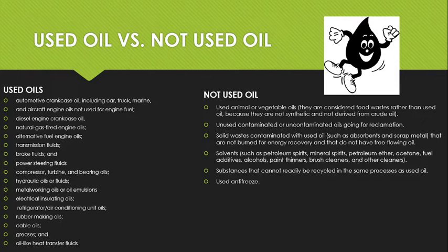So you just really have to pay attention to what you're putting into your oily water, what you're classifying as used oil, because you don't want to screw up a whole load by putting in some paint with your used oil, because that's not used oil. Can't be recycled the same. So it's just important to pay attention to what you're actually adding to your used oil, because it really may not be considered oily water or used oil.